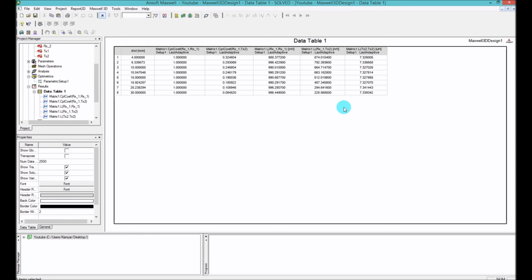The value of the capacitor is 1 divided by F squared times L, and also you have to divide it by 4 pi squared as well. I'm going to use one of those online calculators and come back with the results.